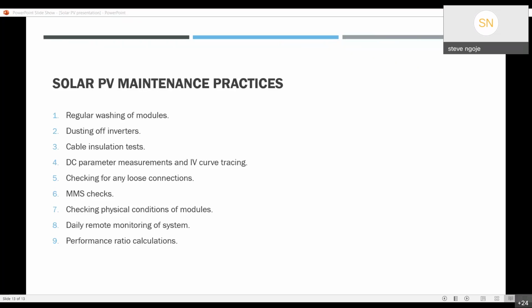So the best way of always doing this is logging power. If it is a large-scale industry or company, Kenya Power has online platforms that also give you real-time data for the consumption, so you can ask for the loggings and get that. Whatever you do, always try as much as possible to log data. If it is a new plant, for example someone just wants to have solar in their house and they're just about to move in, they probably have some equipment.